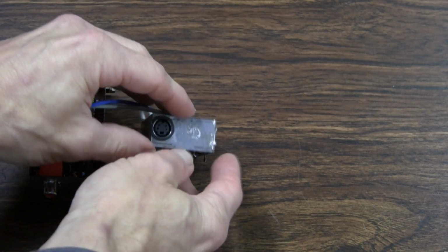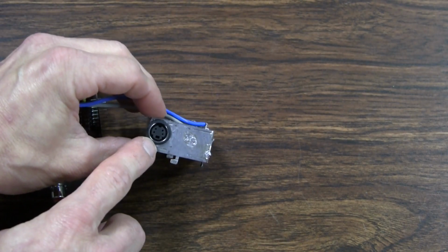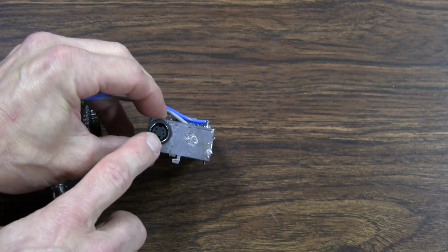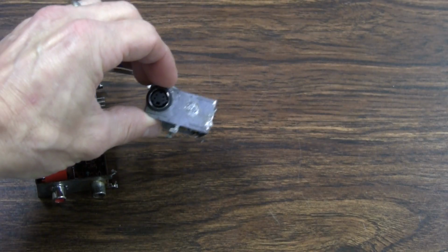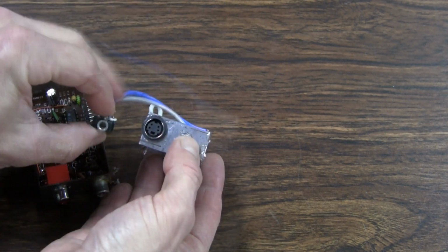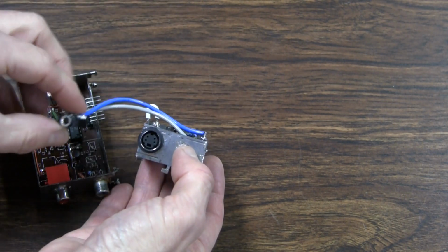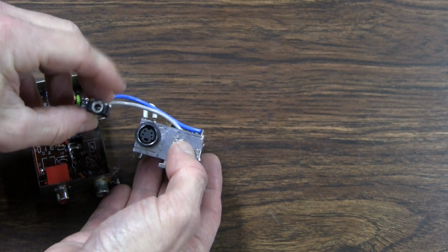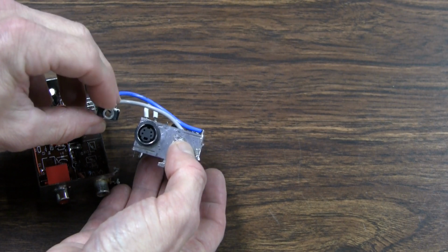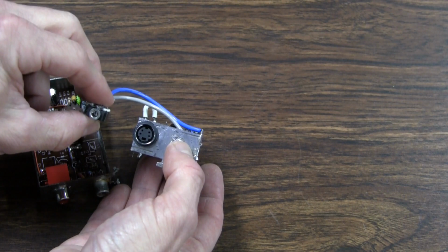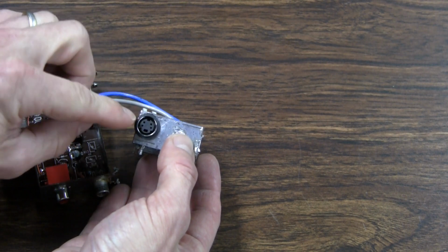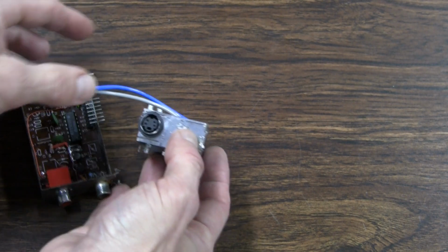On the newer module, I desoldered the old RF output and replaced it with a PCB mount S-Video connector. And in this model, the channel selector switch was external to the RF modulator, so that's the reason for the cabling over to a separate jack. This is an audio video jack for a 3.5mm plug, and we have composite video and audio available on the 3.5mm, and we have S-Video on the 4-pin S-Video plug.